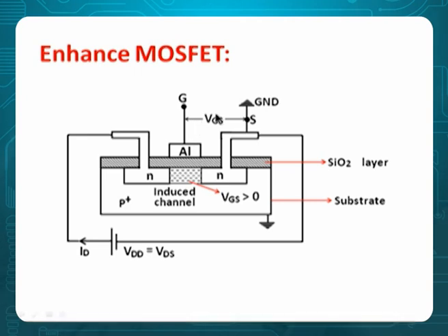Depending on the VGS, if this VGS is positive, it should produce negative carriers, that are minority carriers of the substrate. If VGS is negative, this is supposed to produce positive carriers, that are majority carriers of the substrate. Therefore, only if it is a semiconductor can it supply two types of carriers, depending on the gate supply.